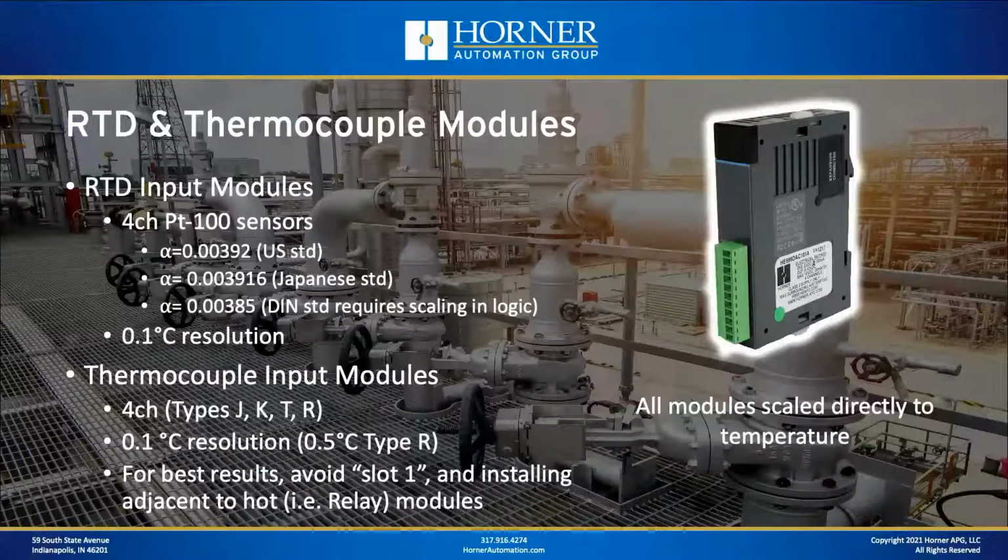Again, it's probably not going to make a large difference, but if you have the flexibility, install your thermocouple cards away from the first slot next to the base and away from relay cards that are providing a lot of current.